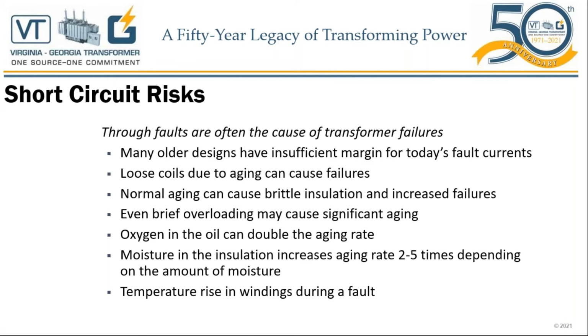So we as suppliers have to make sure that all these leads, the LTC leads, the high voltage, low voltage connection leads, are run through very strong structures and secured very strongly, because those leads, they are in the magnetic field after all. They're going to see short circuit forces.